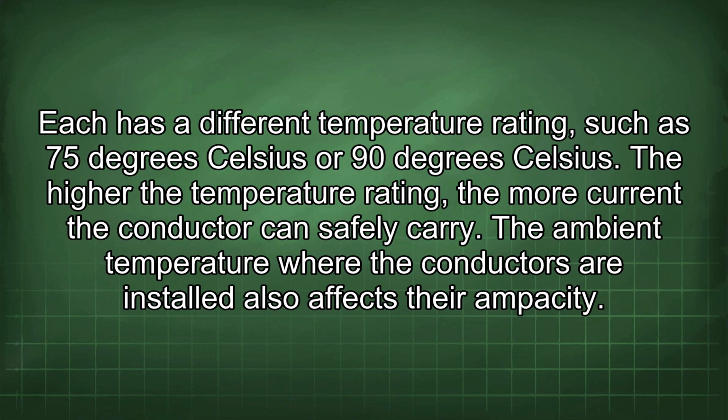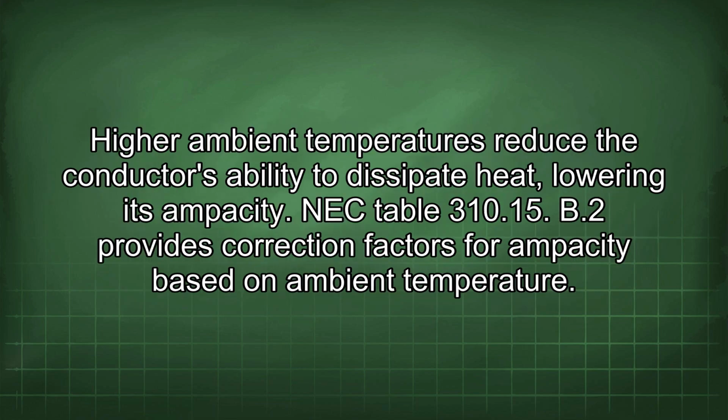The ambient temperature where the conductors are installed also affects their ampacity. Higher ambient temperatures reduce the conductor's ability to dissipate heat, lowering its ampacity. NEC Table 310.15(B)(2) provides correction factors for ampacity based on ambient temperature.